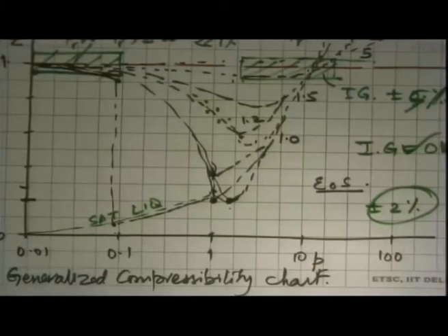So that's what the reduced pressure and temperature actually helps us with, in that we get a common set of pressures and temperatures for which we can compare various different types of materials. Just by looking at their absolute properties, we get very funny looking pictures, which is very difficult to generalize. So that's why we do this.